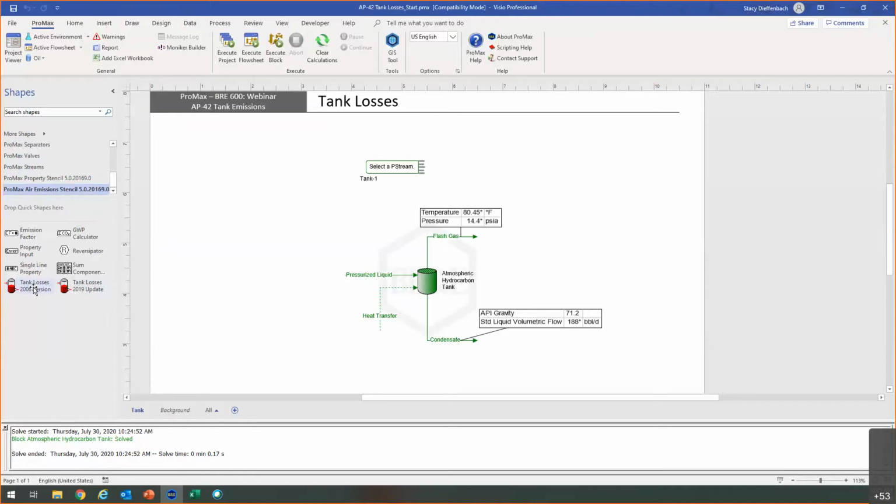For the 2006 version, so far as I'm aware, currently for inventory, if you did your permits with the 2006 versions of the equations, I believe most states are still allowing that to be used for your inventory. Because there are some changes that can make significant differences, it's not really fair to penalize you just because the equations have changed. Many states are requiring that all new permits be done using that 2019 or 2020 version of AP-42 equations. But for the 2006 version, that may still be required for legacy use or for those inventory purposes.